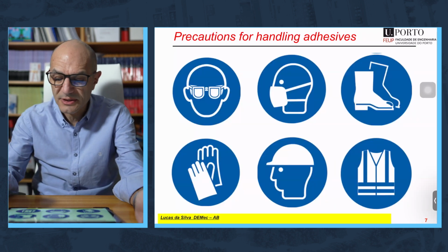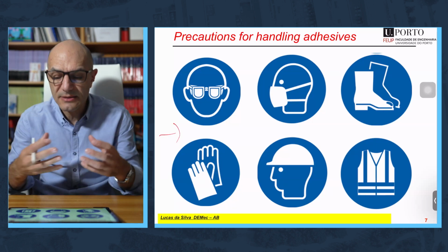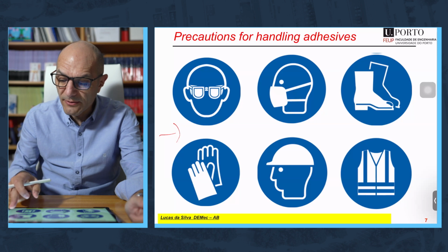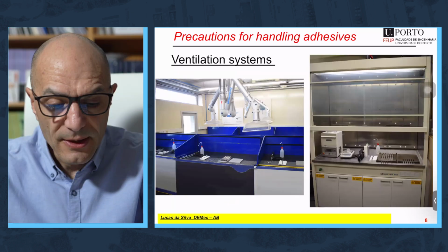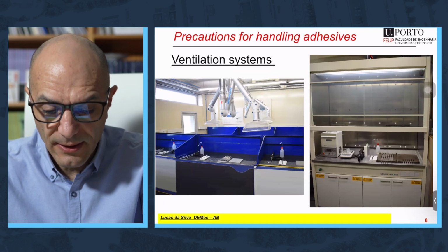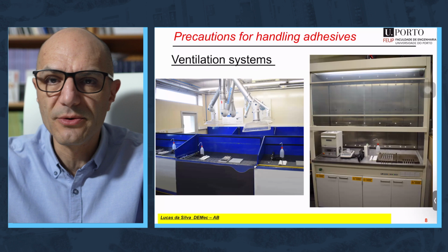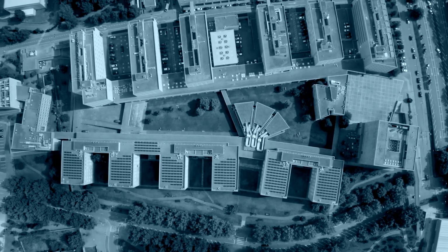We should protect ourselves, and these images are very clear: the eyes, the mouth, feet, etc., to avoid contact with the adhesives. We should use ventilated areas. That's very important, especially for those that release volatiles, fumes, that kind of thing.